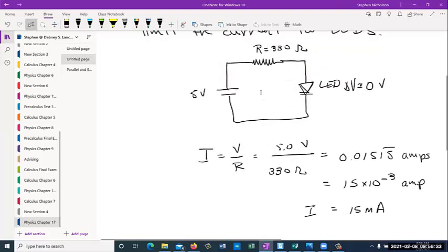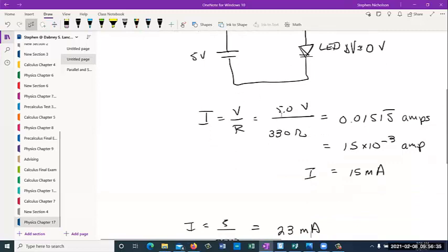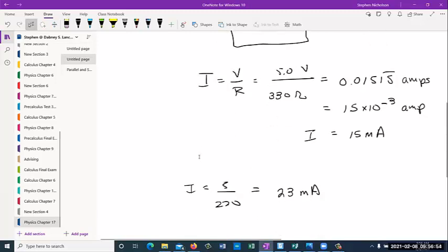But we'll do a lab, like I said, with an unknown resistor. You could use a multimeter to measure the resistance, but if we actually measured the current and voltage for that element, we could take the slope of that line and figure out what the resistance is. Okay, so that's Ohm's law.